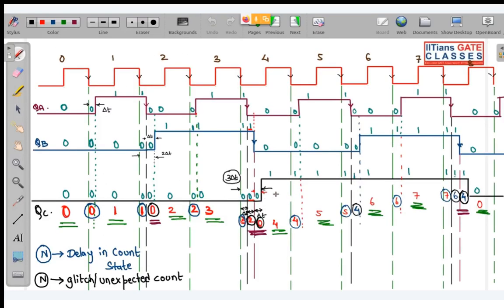Now, for the strobe input to be effective, see, glitches are happening in the negative level. So understand very clearly over here, later on you can copy. This is TCLK, the time period of 1 clock. And this negative level is your TCLK by 2.